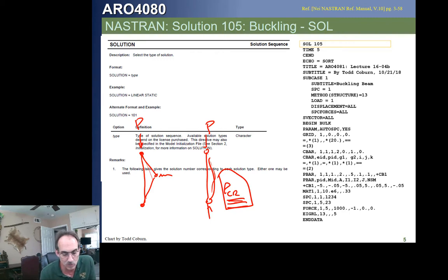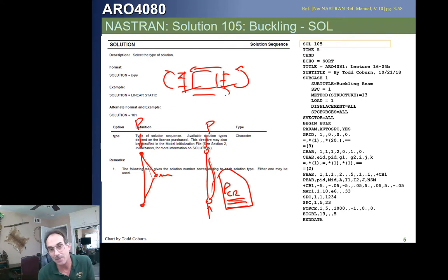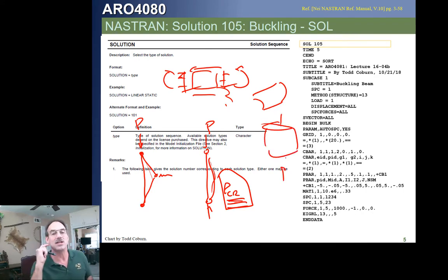Then in 3271 we looked at panels loaded in compression, or loaded in shear, or loaded in bending, and we looked at those failure modes separately and together. We looked at curved panels, and we looked at cylinders for buckling. With all of those buckling solutions, we have to be careful not to buckle our structure lest it not retain the loads.